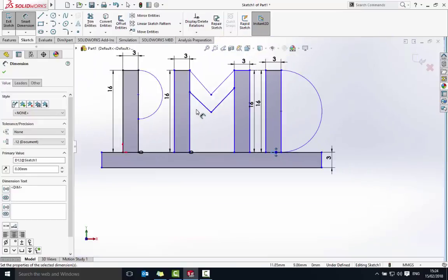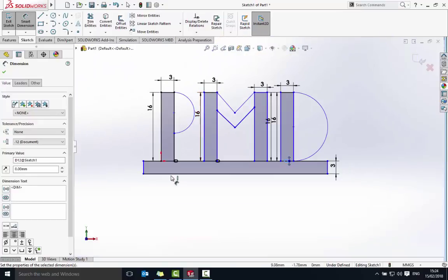So I've got my widths on there, so on the 5 widths there, I've got the 1, 2, 3, 4 heights. So let's think about doing some trimming now, okay? Because at the moment I've got this is kind of a solid piece here, but then it's not connected. So let's have a do that. So to do that, use the trim entities. So click on there,